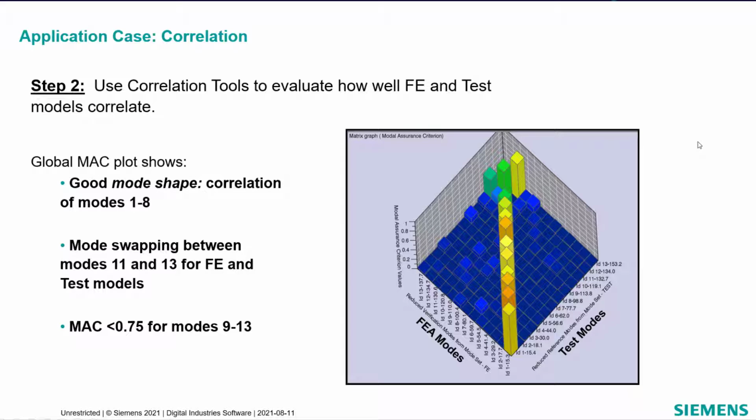So yeah, if we wanted to assess if the shapes are similar, we could do this analysis here, Nick. Mm-hmm. And what do you think of the results? Well, I guess I'd say they don't look too bad. Yeah, we would expect a strong diagonal, right, with high MAC values if the mode shapes are similar between test and FE. Right, but in this case we wouldn't necessarily expect them to all be 1 like we would when we're comparing a set of modes against itself, right?